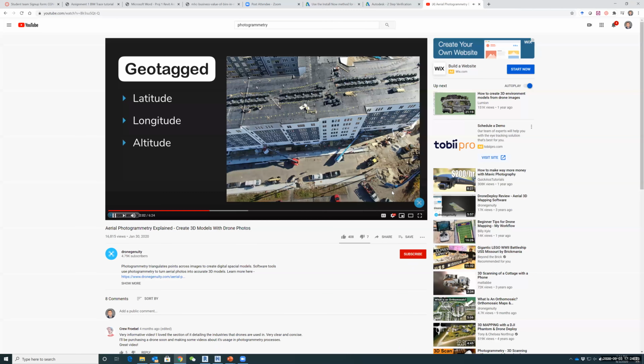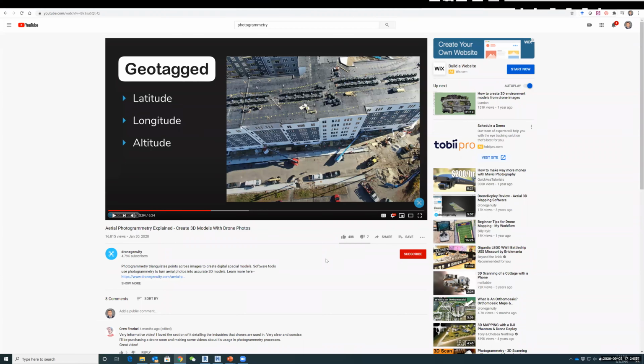That's actually so convenient for construction today. Some companies actually use this in a very smart way. They are doing the earth moving. They fly the drone this week, they fly the drone next week. They overlay the 2 models and boom, the volume difference just shows up automatically. You do not need to do any calculation, it tells you directly. That's photogrammetry. Make sense?